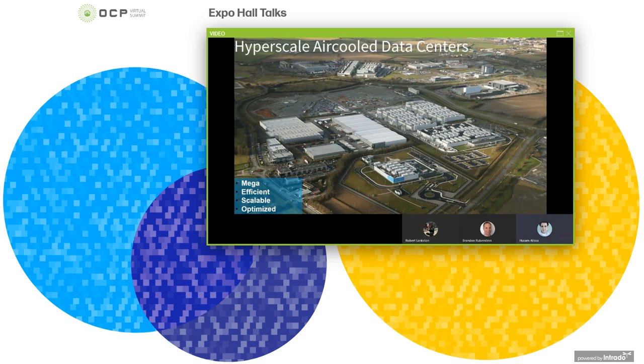And we might end up with mixed low flux and high flux chips based on racks throughout the facility. So we need to make sensible TCO-driven decisions. Do we need water throughout the data center or locally, which could be retrofits that can be rather costly or disruptive, or what we will be showing you here today, which is the use of air assist water cooling.